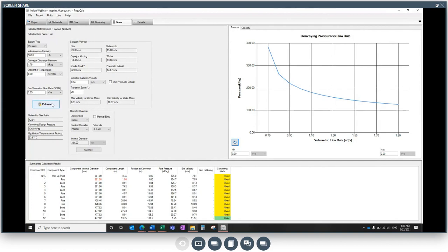So we have accomplished what we wanted to do, and our pressure is at 134, which is below the maximum pressure that we had set for our screw pump. So now if we were to look at this exact same example, but using a dual blow tank line charger, how would we do that in NeuCalc?